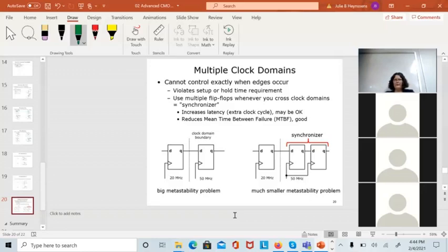Clocks are notorious for being, if it's like a 100 nanosecond clock cycle, that doesn't mean it's high for 50 nanoseconds and low for 50 nanoseconds. It's high for 40 nanoseconds and low for 60 nanoseconds. So the timing is not just a factor of 2 you have to worry about, it's more like a factor of 4 to get everything lined up. And yeah, I spent like weeks on that circuit. I got it to work. But okay, so just don't do this.